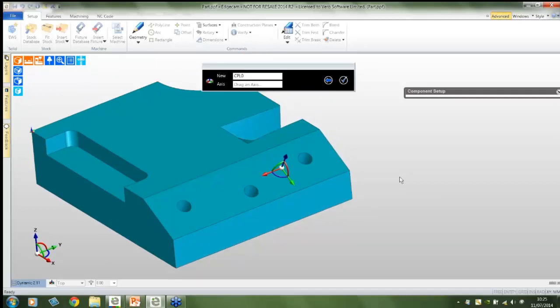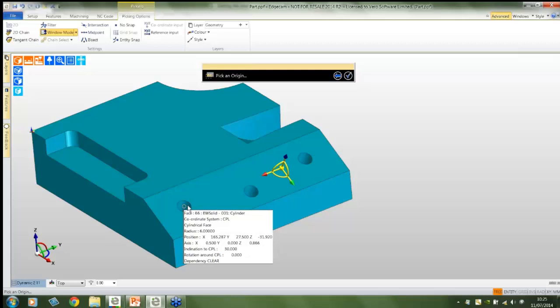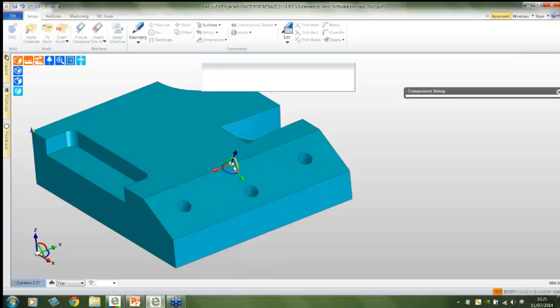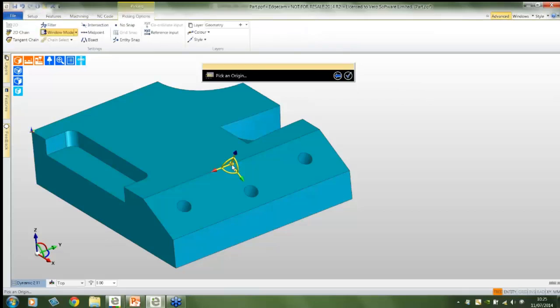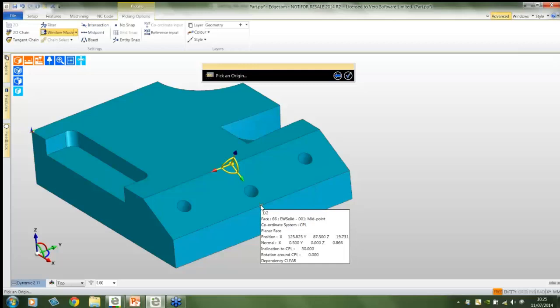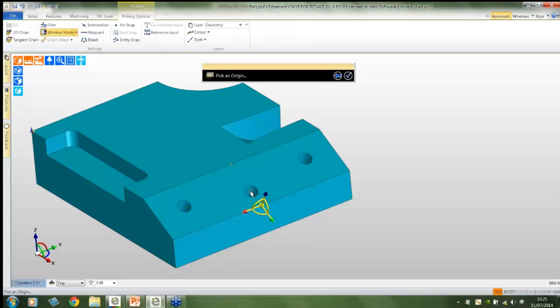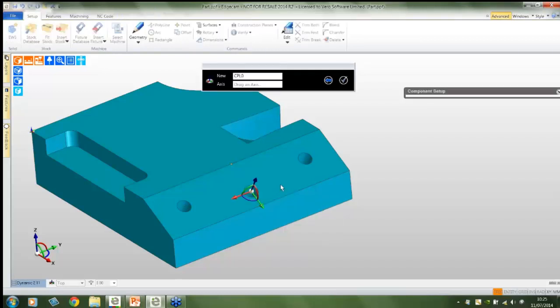So okay, we've got ourselves onto the face, but we're not quite there yet. As you hover over the center of the orbit, you'll see how it all glows yellow. When we click that, you've now got the ability to move this to wherever you wish. So that's how you move its origin, by waiting for the yellow to glow. Notice that I can go to the midpoint of an entity, and very easily I can go to the center of an arc. Sometimes they were difficult to grab. Now you can see it's extremely easy. So again, that's a little covert enhancement.